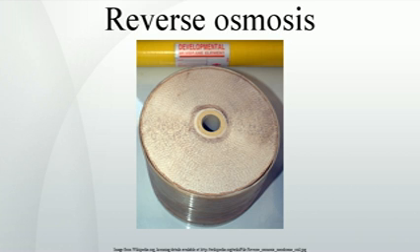Pre-filtration antiscalants. Scale inhibitors, also known as antiscalants, prevent formation of all scales compared to acid, which can only prevent formation of calcium carbonate and calcium phosphate scales. In addition to inhibiting carbonate and phosphate scales, antiscalants inhibit sulfate and fluoride scales and disperse colloids and metal oxides. Despite claims that antiscalants can inhibit silica formation, no concrete evidence proves that silica polymerization can be inhibited by antiscalants. Antiscalants can control acid-soluble scales at a fraction of the dosage required to control the same scale using sulfuric acid.